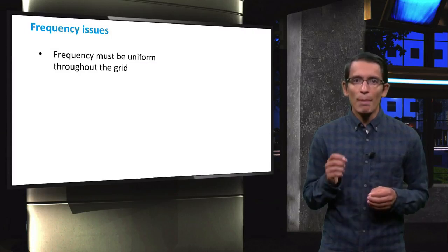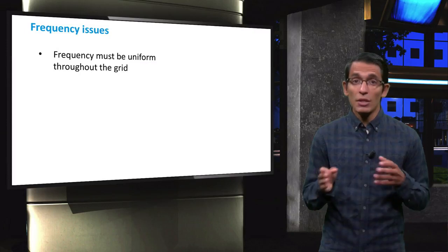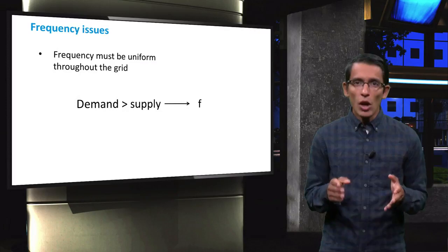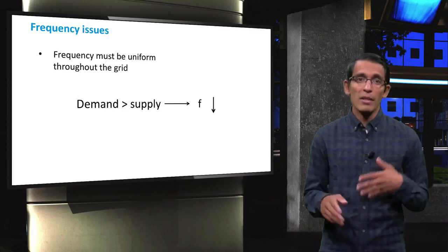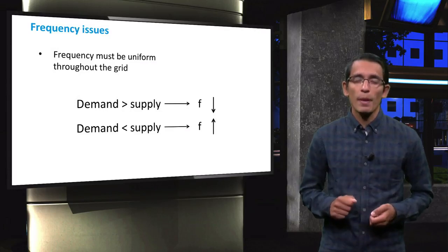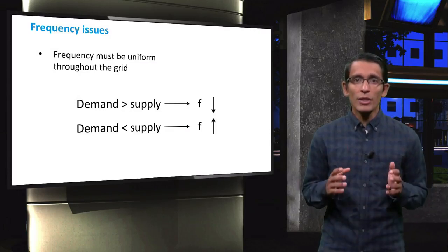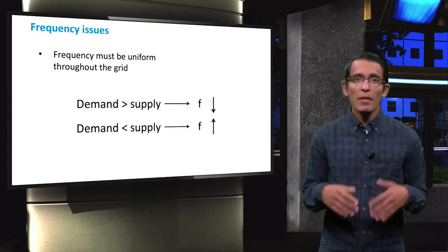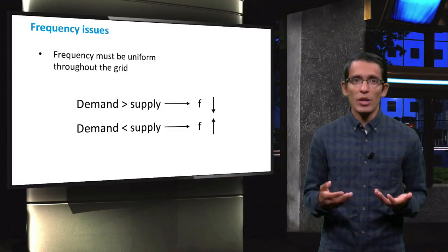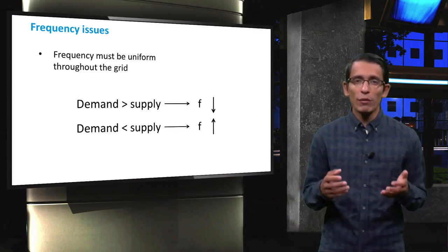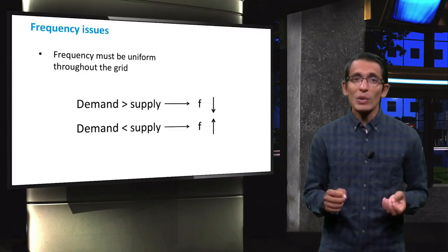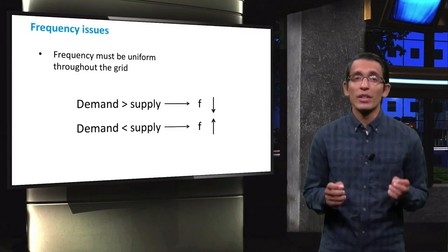Also, disruptions in the balance between the supply and the demand lead to frequency fluctuations. In particular, the frequency of a system falls when demand exceeds supply, and in the other way around, frequency rises when the supply exceeds the demand. Again, with less controlled distributed generation like PV, this becomes increasingly difficult to control and monitor. With increased PV penetration, there is an increased chance of power fluctuations, which can result in frequency fluctuations. These frequency fluctuations can be very damaging to the loads connected to the grid.